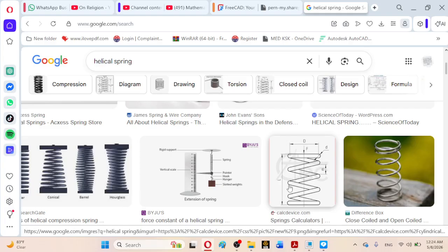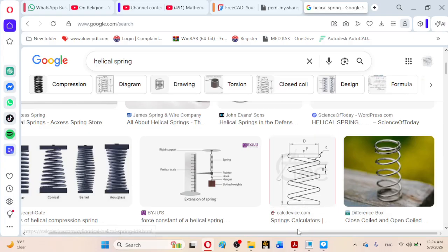this is the second pitch point, and this is the third pitch point, and this is the fourth pitch point. So all pitch points will be connected by a straight line, which will actually be acting as the trajectory. That means a straight line connecting these pitch points will be used as the trajectory for the sweep command, and the wire diameter will be used as the sweep section for that trajectory for pitch points.